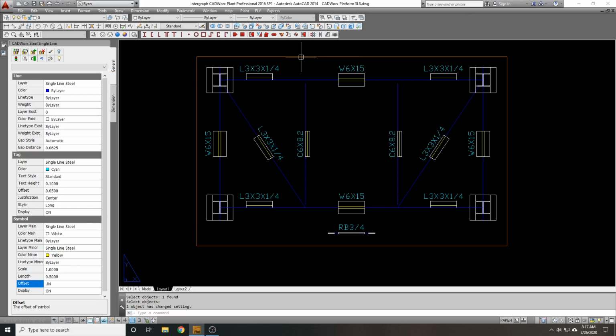However, you can make changes to one member at a time. And I'll get to that in a second, but keep in mind that if you do apply settings and click one member, it'll make the changes only to that one member. Also, it treats it like a manual override. Now that you have applied the setting manually, if you go back and do a viewport application, it might adjust the settings for all the other ones, but not that one.